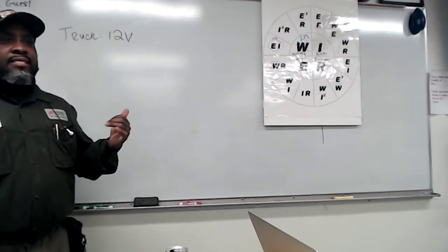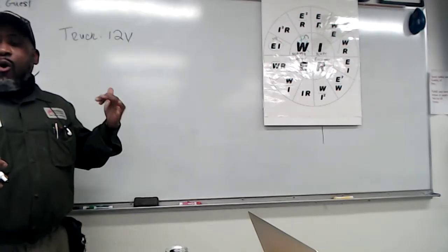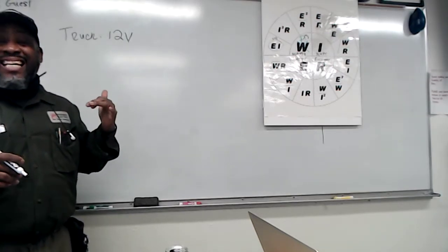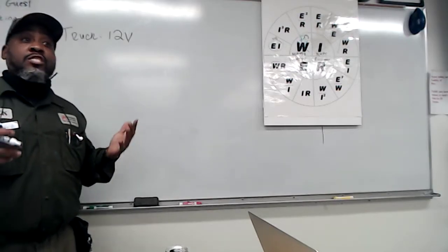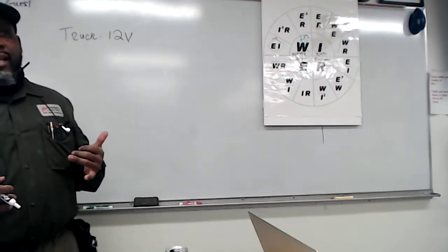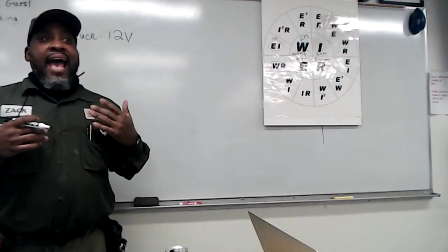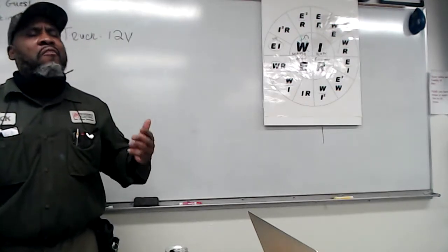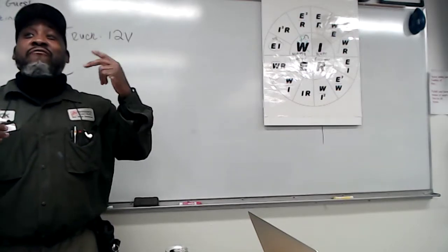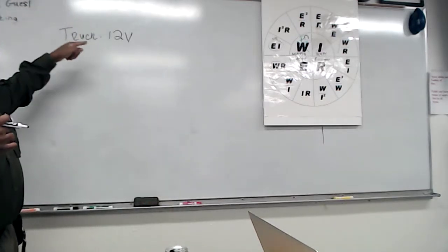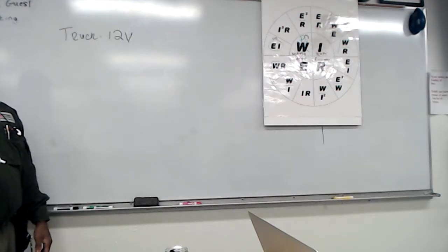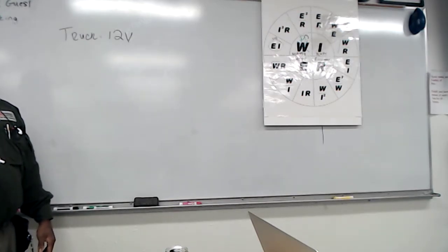A starter is simply a DC motor, okay? The starter requires more current than can be delivered by a single 12-volt battery. It's telling me a single 12-volt battery ain't going to get it. But I got three 12-volt batteries. How can I make three 12-volt batteries work for this 12-volt truck? Parallel circuit. Make sure amps go up.